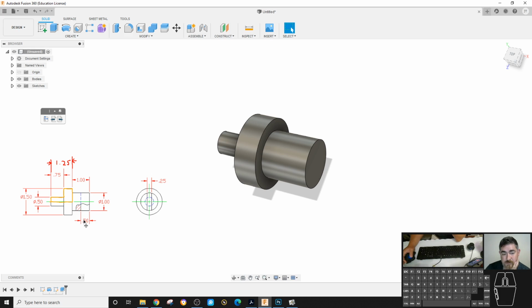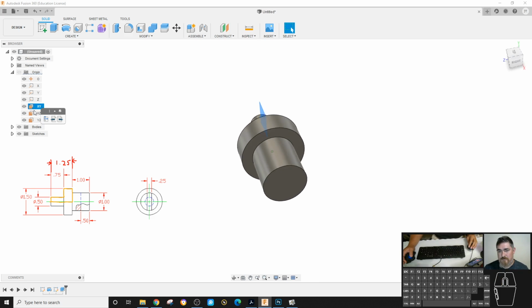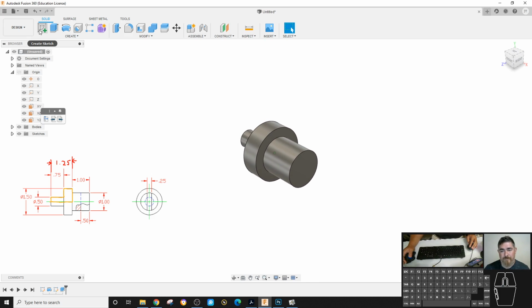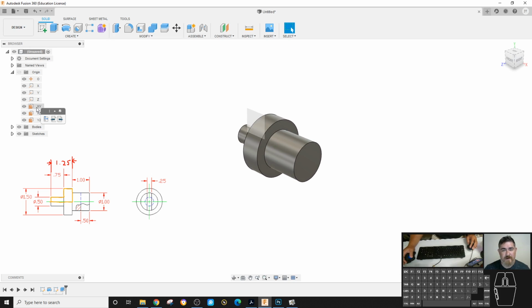It's all the way through, it's 1/2 inch deep. So a couple things, I could draw it here, or I could draw it on that plane, going down the middle. Either way, it's probably easier just to draw it here, because that way I don't have to create that and then project the intersection line and everything.